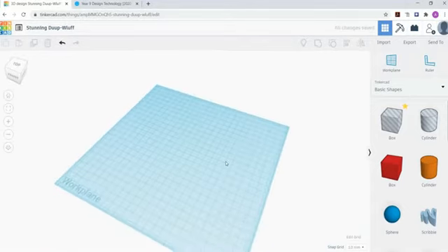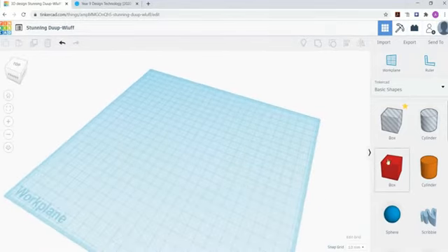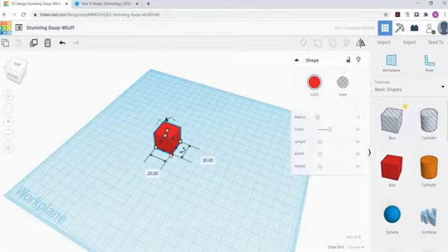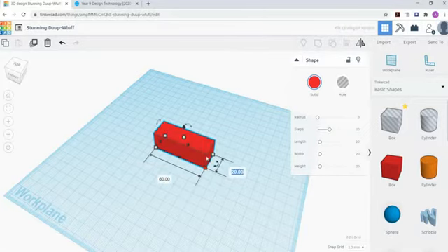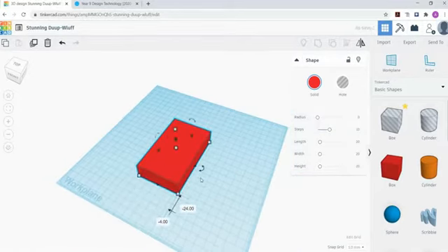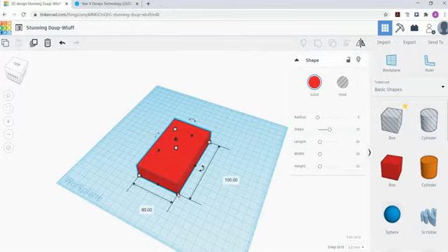So the first thing that we need to do is use the basic shape, drag the box, and then change the dimension. I think we will use the last dimension that we used for our rectangle, probably 60 by 100 again, and we're just going to let the height remain the same. We're going to make a curve over here. Sorry, what I'm going to do probably, yeah, put 100. I'm going to make a curve over here.